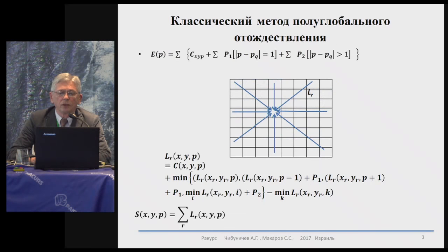At the next stage, we have to add values depending on the changes of the lateral parallaxes from pixel to pixel. We analyze these changes based on 8 different directions, and this is what semi-global matching of these points is all about. We analyze all pixels. For each pixel we analyze absolutely all neighboring pixels.